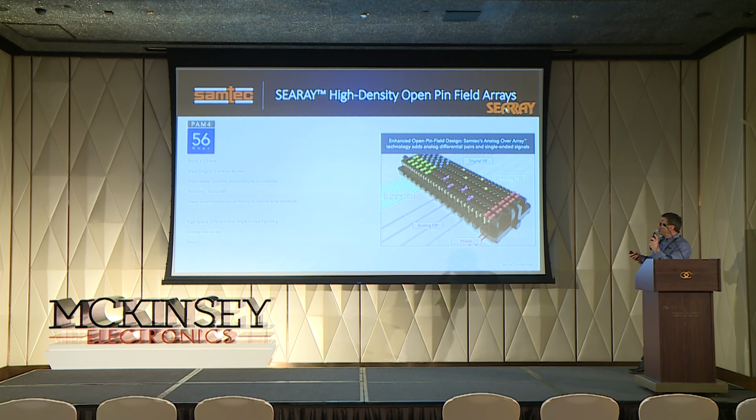And this next image here gives the view of what you can really do with an array series as an open pin field, because no pin is defined for any particular function other than your pin mapping. So if you want to do differential pair, single-ended, analog single-ended, power, or just signals, you can define your pin assignments accordingly.